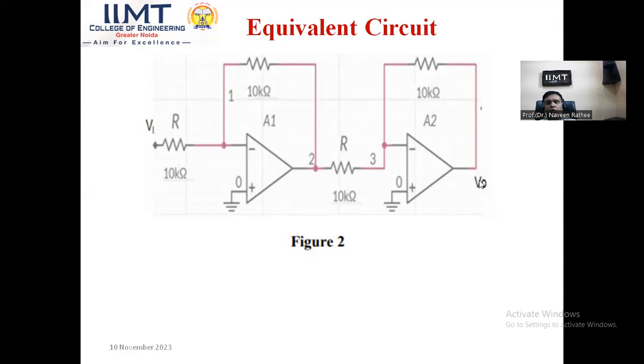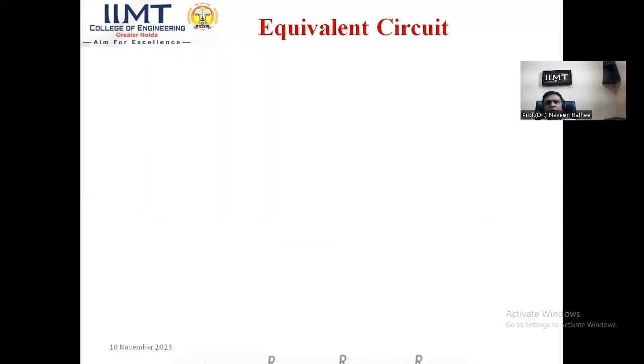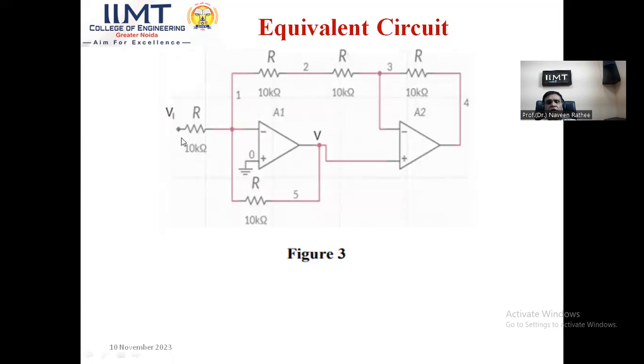Now, coming on to the equivalent diagram for the negative half cycle. So when negative half cycle is available over here, negative is connected with a negative. So diode D2 was conducting. When D2 is short circuited, upper one diode D1 was open circuit, so it gets cut out from the circuit. So the path which is being followed is this now.